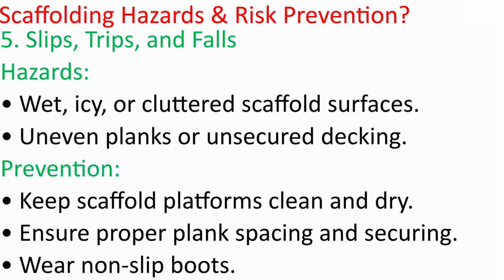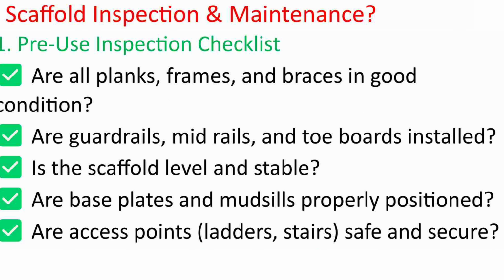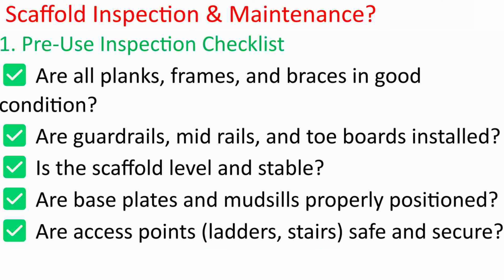5. Slips, trips, and falls. Hazards: wet, icy, or cluttered scaffold surfaces. Uneven planks or unsecured decking. Prevention: keep scaffold platforms clean and dry. Ensure proper plank spacing and securing. Wear non-slip boots. Question: what is the scaffold inspection and maintenance?